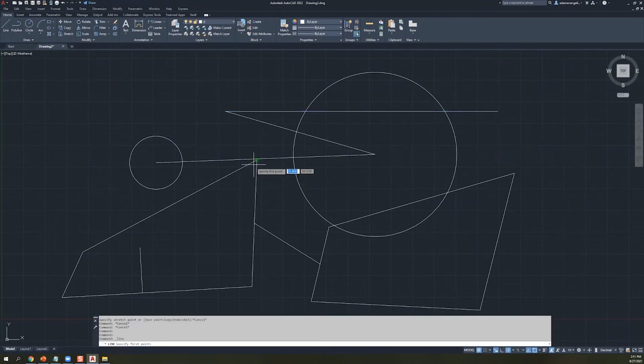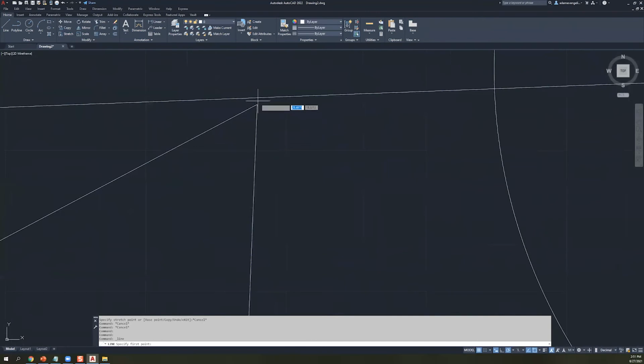I believe it's something I've heard called scrubbing. So, you can scrub a point a little bit, and once you scrub off like that, it's going to leave that little mark as a point of interest that you could then do horizontals to, or extensions, I suppose, if you need them. And you can do multiple lines like this too. So, mouse over a certain point, and now you can do that over here as well. And the previous ones are still persistent.